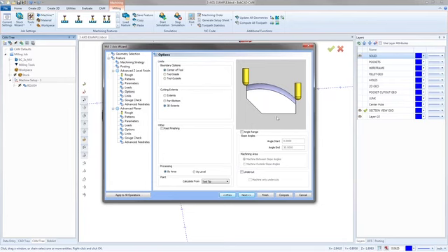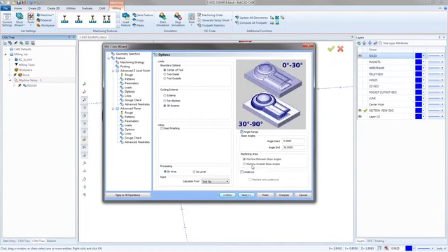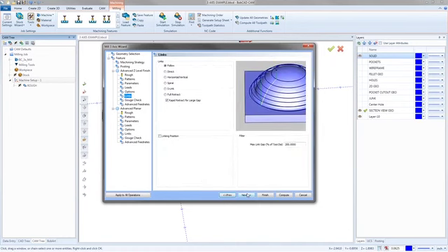Right here's the good stuff. It's the angle range. So for this toolpath, and I'm telling you, the toolpath does not like to cut flat floors. It doesn't like to cut anything really below, I'd say, about 35, 40 degrees. Anything lower than that, and this Z-level toolpath doesn't even want to do it. So what I can do is say, let's do an angle range. Let's limit this toolpath to only cut the areas that it's good at cutting. So I could say start at 30 degrees and end at 90 degrees. Then I'll hit next. So now I'm saying machine between those angles. So on the next one, I can get it to clean up what's not getting cleaned up right now.